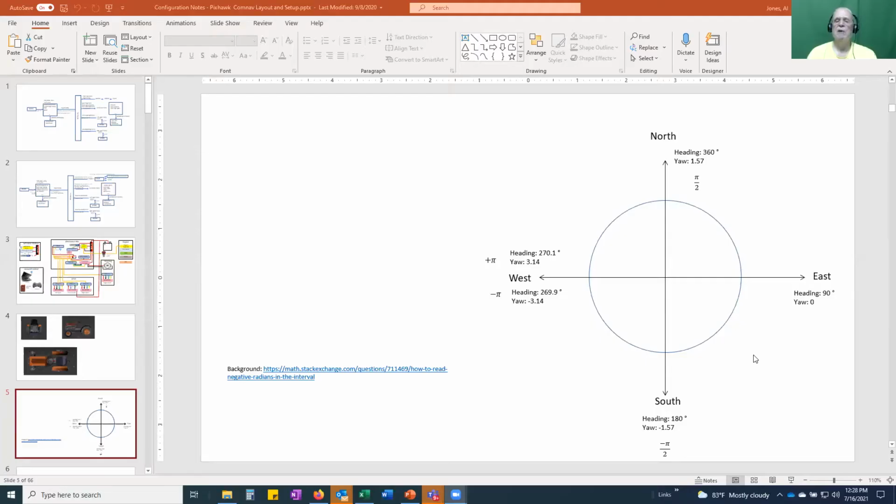The more I dug, I found that now that's been moved back into the NMEA Navsat driver. I see there's been a lot of hacking done on that. It directly publishes that heading quaternion, so you don't need gps_heading.py at all anymore. It also publishes a speed value. There are various things in there talking about fixing errors, and something about generating NaN values based on something.